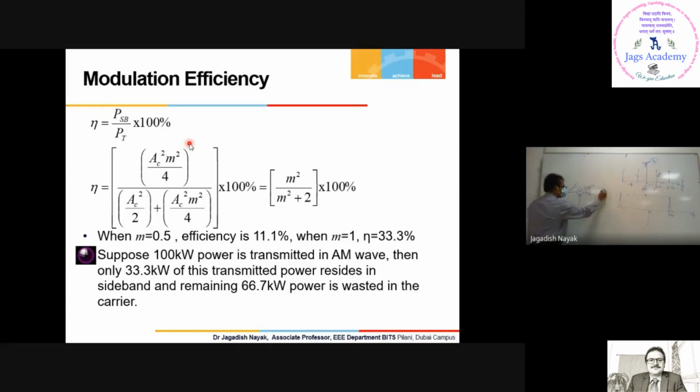After that, here you use a band pass filter, which is called as notch filter, which has a very sharp band of frequency to be passed. Right? And the bandwidth of that filter has to be around fc plus fm, so as to keep upper side band and remove lower side band. Okay, that is this one. Okay, so now you know that convolution in time domain is equal to multiplication in the frequency domain.